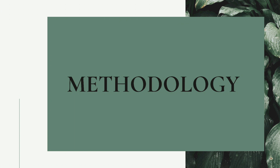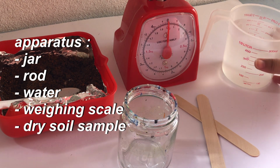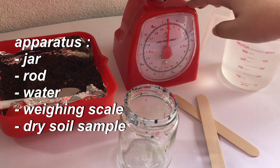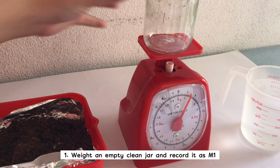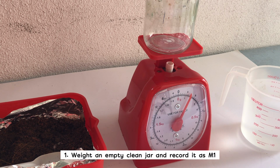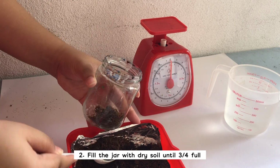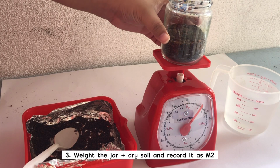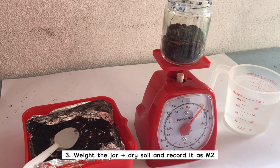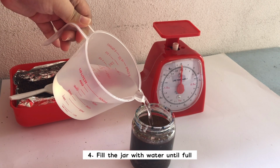For the particle density test, the apparatus needed are jar, rod, water, weighing scale, and dry soil sample. So for the first step, weigh an empty clean jar and record it as M1, and then fill the jar with dry soil until 3/4 full. Next, weigh the jar plus dry soil and record it as M2, and then fill the jar with water until full.